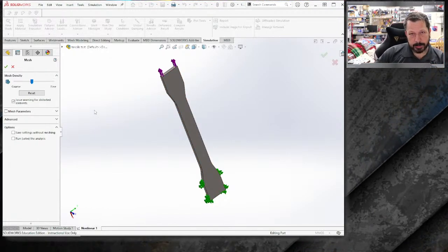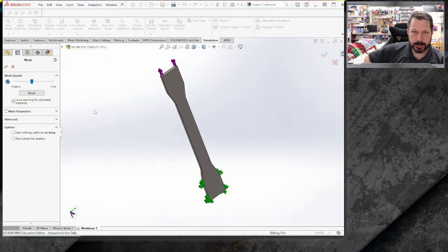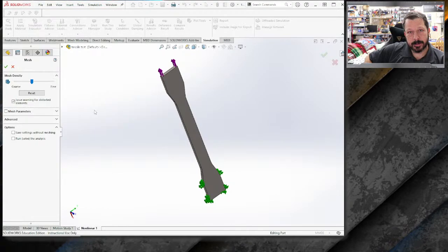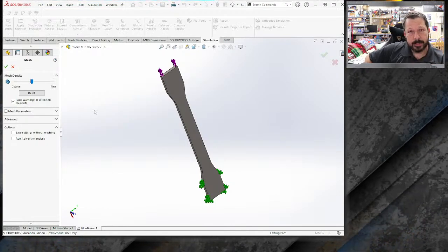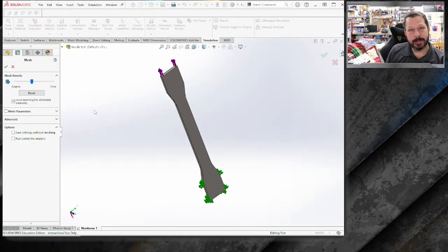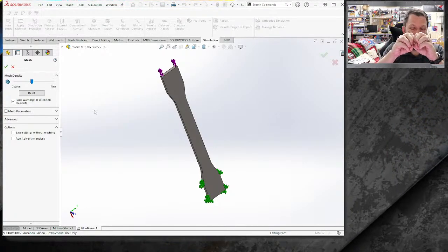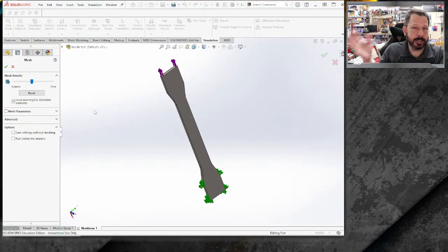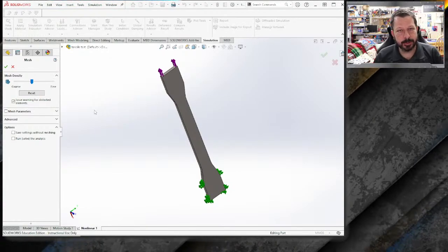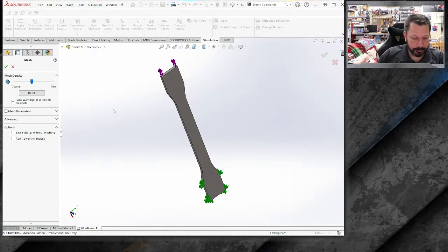And how finite element deals with that is that instead of looking at this as one piece, one tensile test specimen, it divides it into thousands of finite individual elements. And so it will analyze each one of those elements individually and connect them together. So I've got element A here, it's touching this other element B, and so that boundary between them must share something in common. And so it will figure out this. It's a big giant linear algebra type matrices that gets done in the background of the computer.